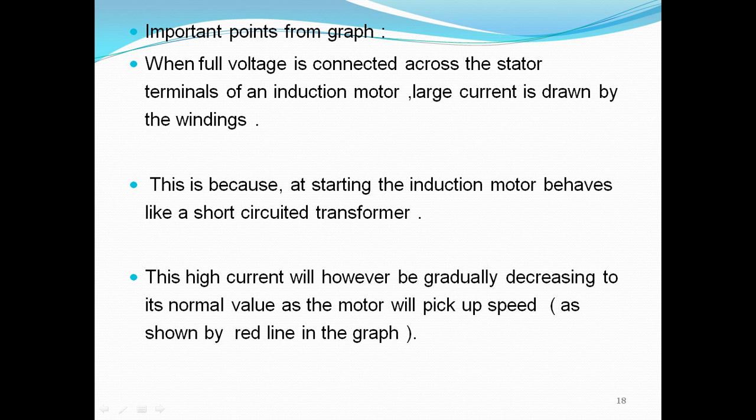Since the contactor coil gets the supply through the contactor contact, it is called the hold on coil. If you press the off button, the coil gets de-energized and the contacts open. If supply fails or line voltage drops below a value, the contacts open, and this is called under voltage or no voltage protection.